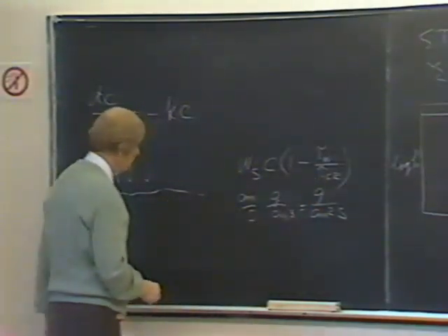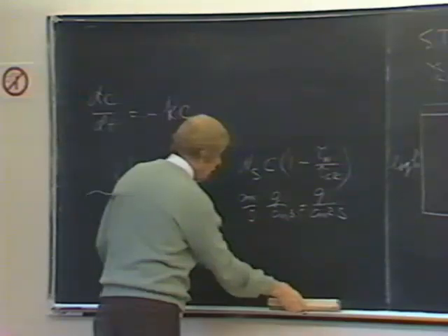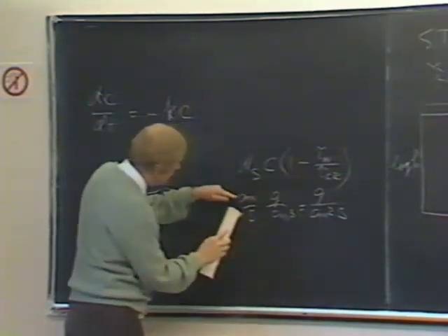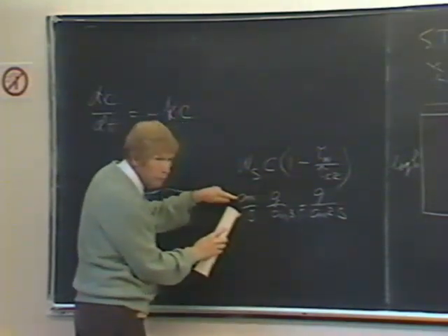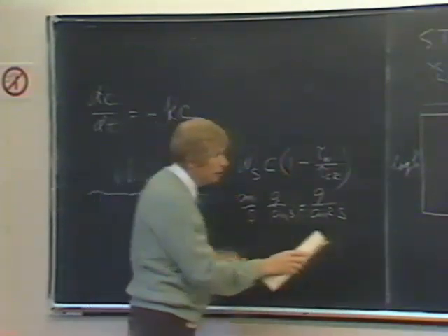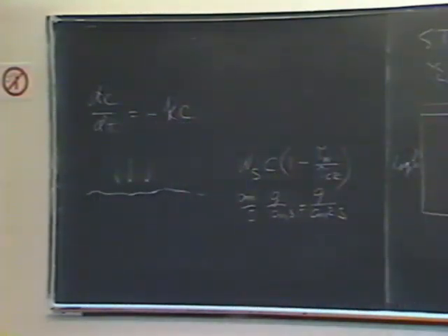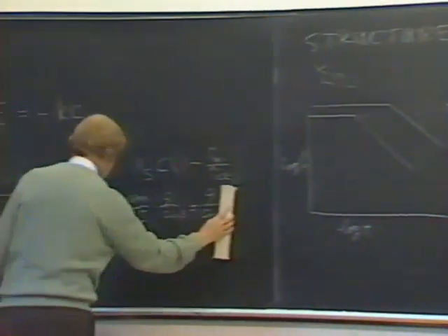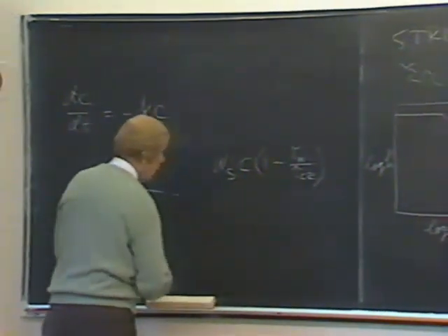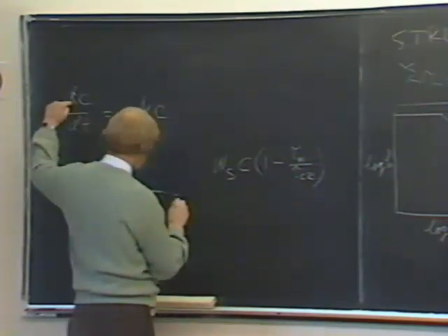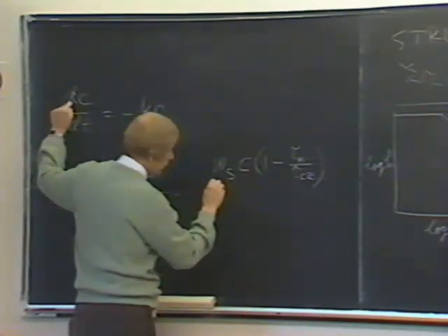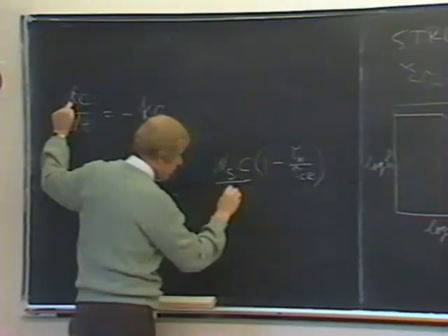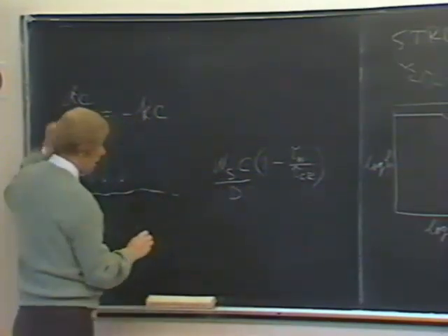Now, our flux removes the particles from the mixed layer above it. Above this, we need to account for that. So we can describe the change in concentration of suspended material as this divided by the depth. I'll call it d. And that's our dc dt.